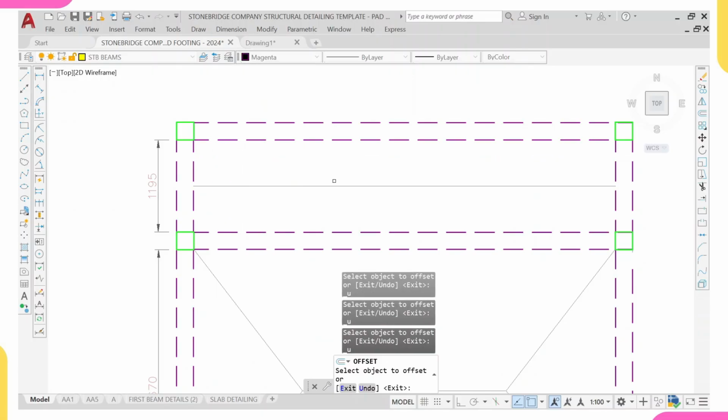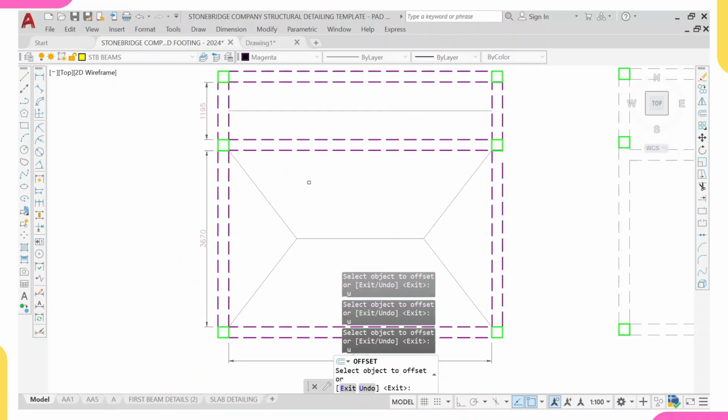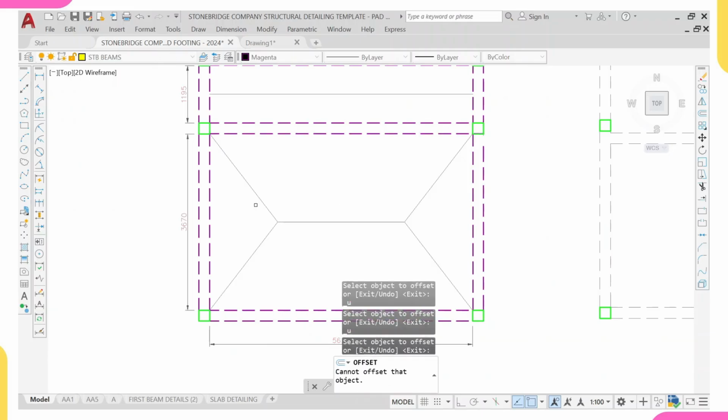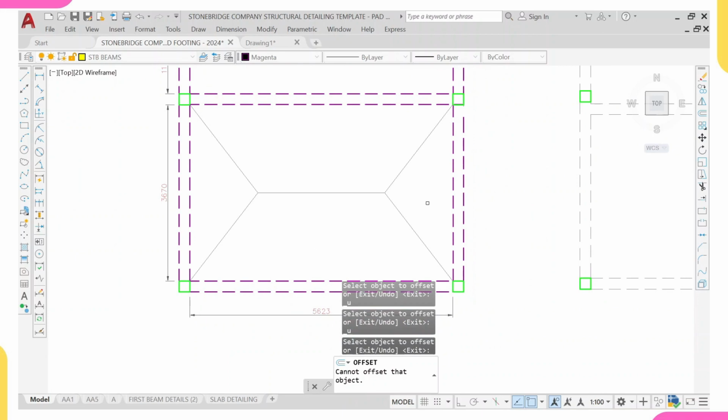So coming over to a two-way slab. This is a two-way slab. If the load is being shared like this, remember this is the longer span. So the longer span will carry this trapezoidal load. You're seeing a trapezium here. This side will carry this triangular load, and here will also carry this load, and here too.